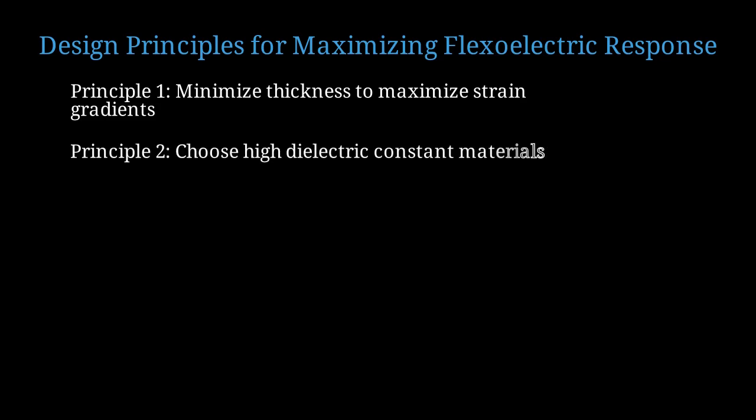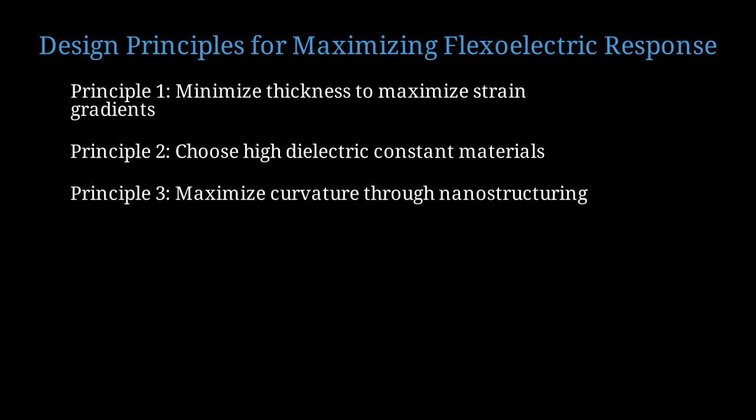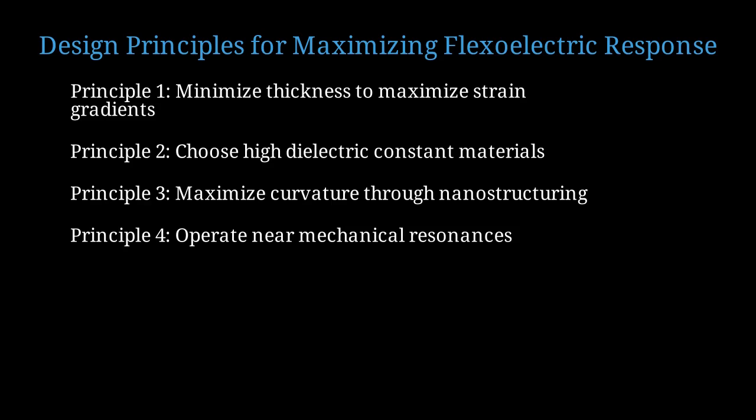Second, select materials with high dielectric constants, as flexoelectric response scales with dielectric susceptibility. Third, engineer structures with maximum curvature, such as highly bent membranes, wrinkled films, or nanostructured surfaces. Fourth, for dynamic applications, operate near mechanical resonances to amplify strain gradient amplitudes by the quality factor.